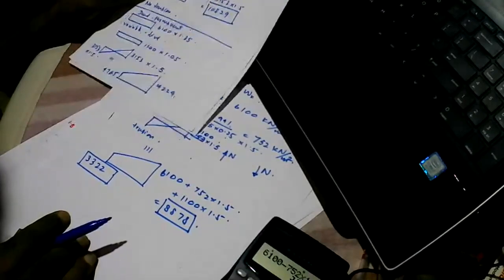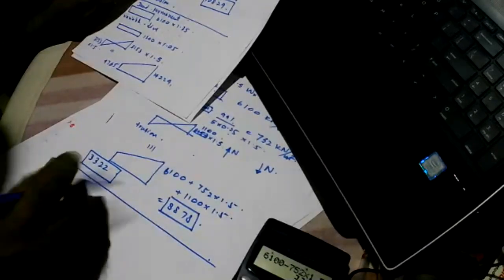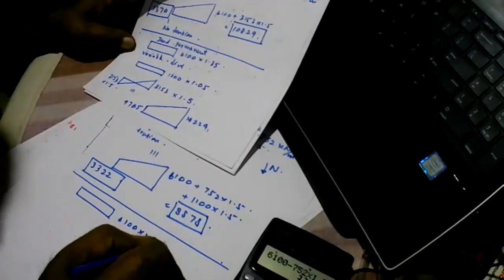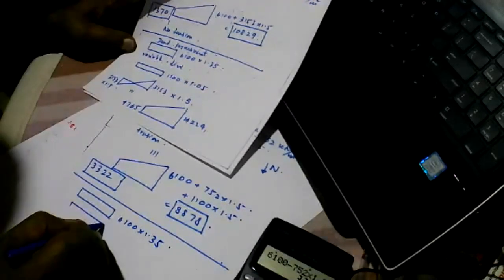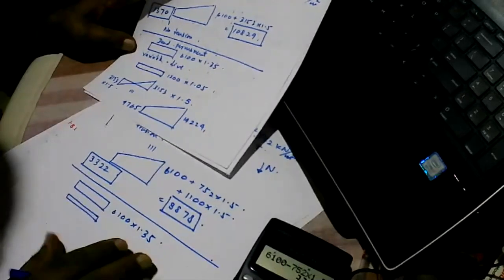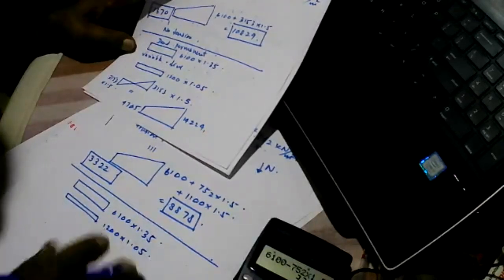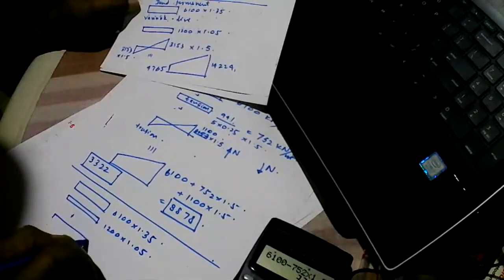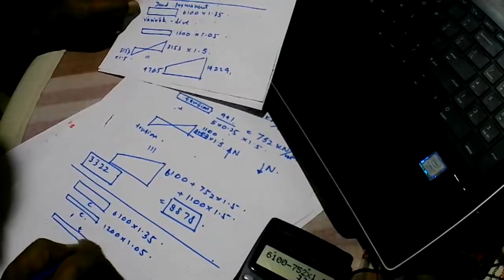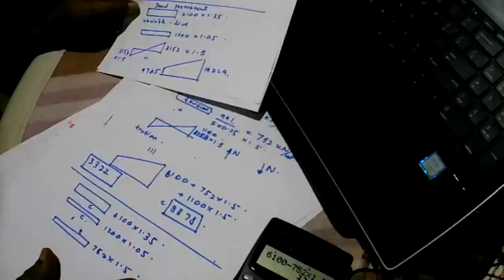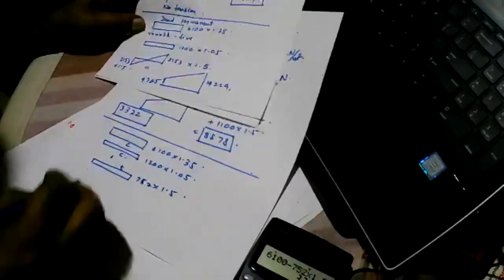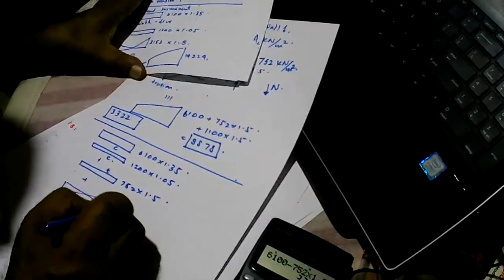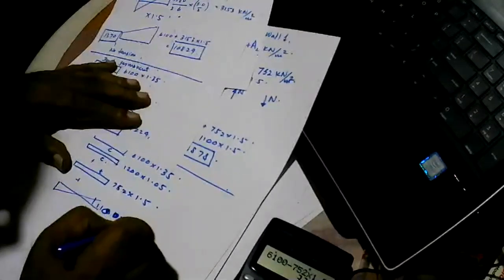Then we can also consider the other critical case, and that is dead permanent, or the permanent 6100 multiplied by 1.35, and then we get tension again, live load 1200 multiplied by 1.05, and then we get tension happening like this compression, this tension 752 multiplied by 1.5, and also we get wind, that is 1100 multiplied by 1.5.